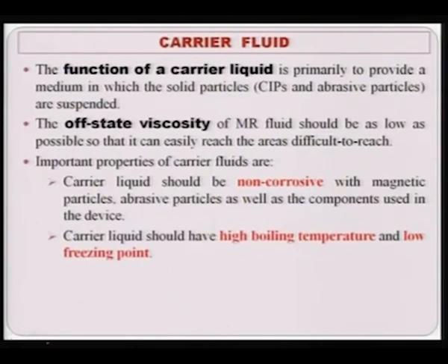Carrier liquid should have a high boiling temperature and a low freezing point, because heat is generated to some extent, and definitely the carrier fluid should not start boiling, otherwise it will not be able to serve its purpose properly. It should have a low freezing point, because in many locations the environmental temperature is low, and it should not freeze, otherwise it will not serve the function for which the fluid is to be used.